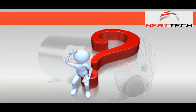They actually have a non-return valve on the cold water side. That's how they do their installations. Now, Herman says technically it is sound that you can put a non-return valve in, because then you won't have any flow out of your geyser. However, sorry to say, guys, the standard says you've got to have a vacuum breaker in the system. So, unfortunately, it sits like that.